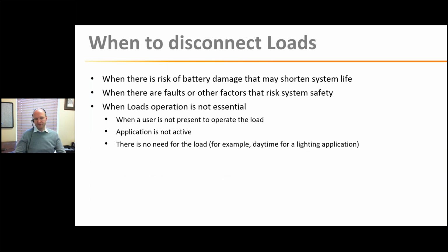So when will you disconnect loads? Well, the main purpose of our controllers is charge control on the charging side and load disconnect on the load side. Those are the 2 primary functions that our variety of products enable. And there's a risk of battery damage due to deep discharge, whether it's lead acid, which becomes more damaged over time if it's too deeply cycled, or lithium batteries, which really can't go below a certain point or else they sustain critical damage pretty quickly, and they can also disconnect internally. So we're trying to prevent that from happening.